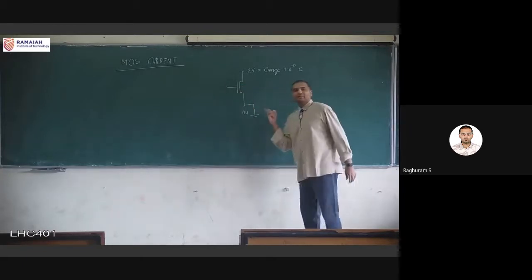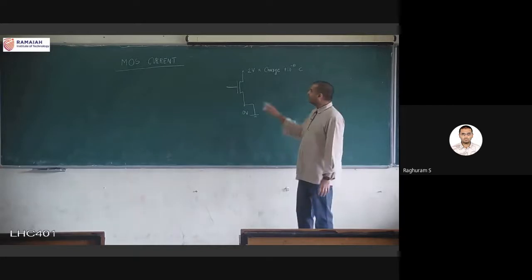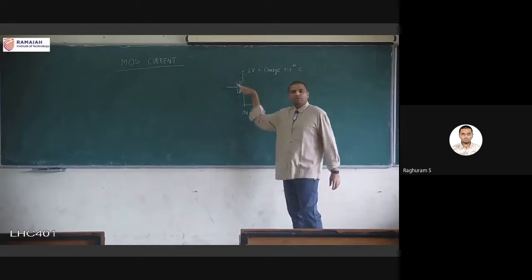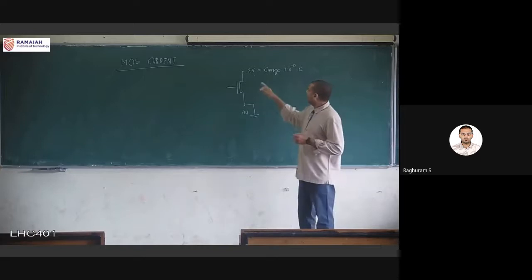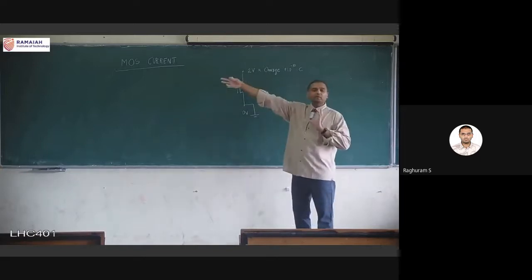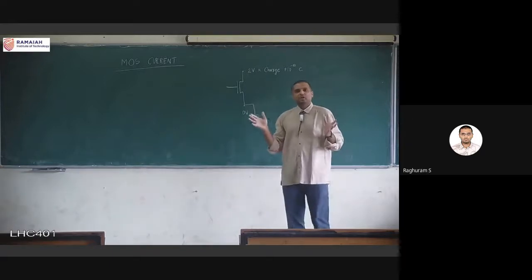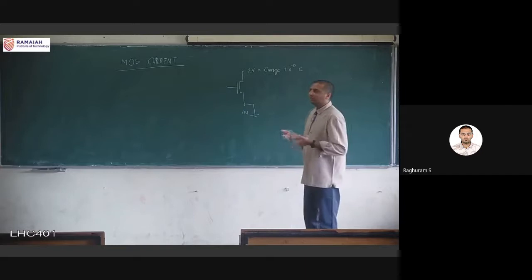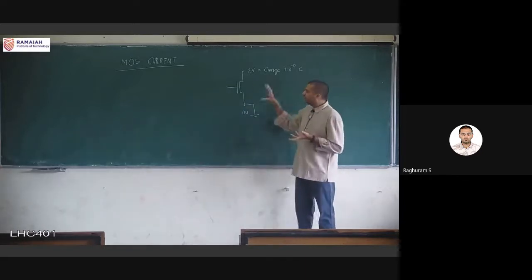This is where the transistor and the current come into the picture. Any circuit is going to be connected like this between the 2 volts and the 0 volt. So if the transistor current is very small, then it takes a long time to go from 2 to 0. If the current is large, then very quickly it will go from 2 to 0. So that is why we need the value for the current expression to find out for this particular case.